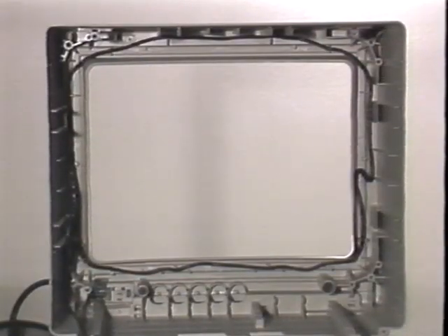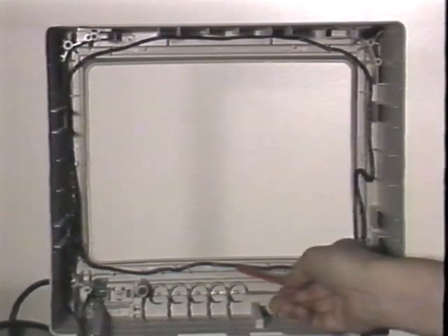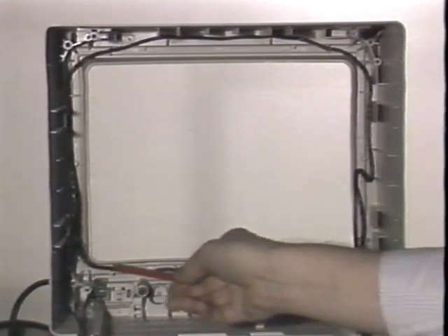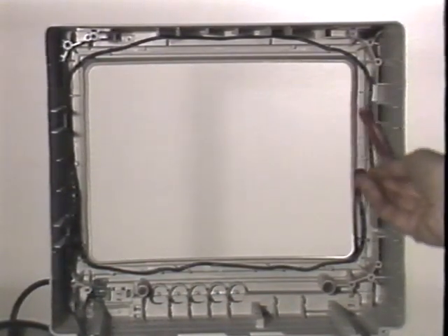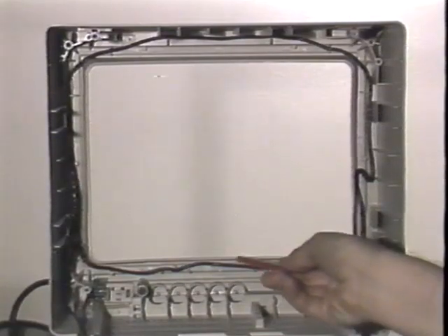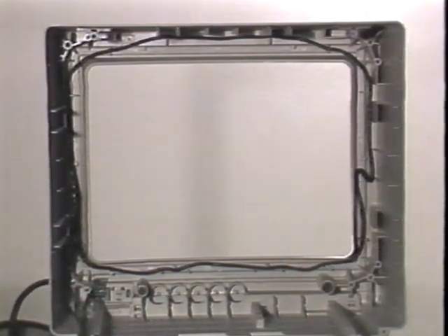A final important peripheral part found in color monitors is the automatic degaussing coil. This looks like several strands of wire wrapped around the outside of the CRT. A current passes through these wires on power-up, hopefully removing any residual magnetism from the shadow mask. Occasionally, the tube may still need to be manually degaussed.